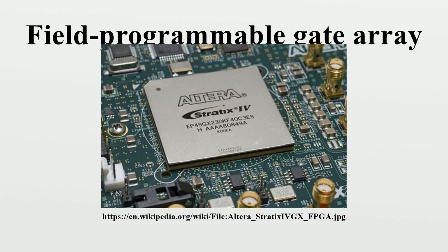The extensible processing platform enables system architects and embedded software developers to apply a combination of serial and parallel processing to their embedded system designs, for which the general trend has been progressively increasing complexity. The high level of integration helps to reduce power consumption and dissipation, and the reduced parts count versus using an FPGA with a separate CPU chip leads to a lower parts cost, a smaller system, and higher reliability, since most failures in modern electronics occur on PCBs in the connections between chips instead of within the chips themselves.